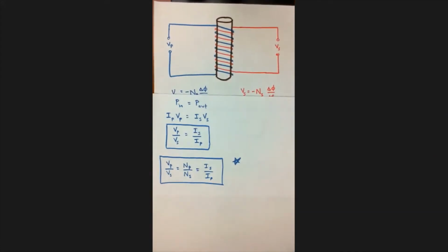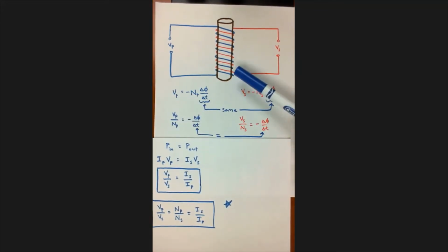If you want to produce DC voltage, you have to do things like add a split ring commutator, add coils to the armature. You have to do some extra stuff to make it DC. So it's more convenient to use AC electricity on the electric grid because it's what generators naturally produce in the first place. And the second reason is because we can use transformers.